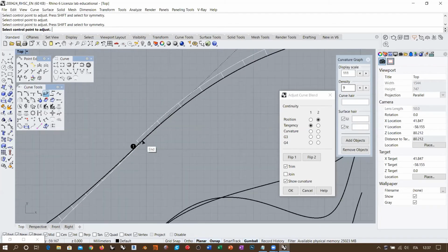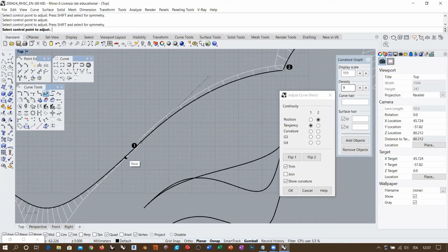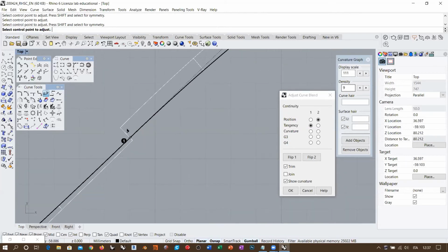Okay, this means that this curve has some curvature oriented to the left, while this one has some curvature oriented to the right. Sorry. Remember that the curvature graph appears on the convex side of the curve. So there is a total jump in the value and in the sign of curvature in this point.